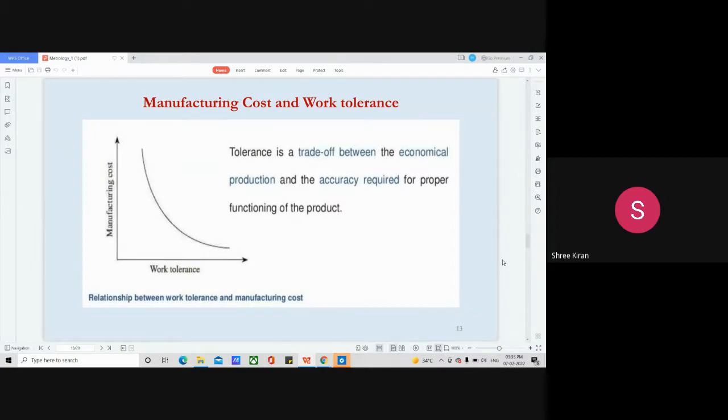Then in this case, the no-go gauge or plug gauge, all these factors play a very important role. These gauges not only control the diameter in any given section, but also ensure the shaft alignment or the bore's alignment. However, the degree of ovality cannot be checked using the gauges, but it can be checked by replacing a pin with pins of different gauges. That's what happens in the case of gauges, with the help of the basic Taylor's principle.